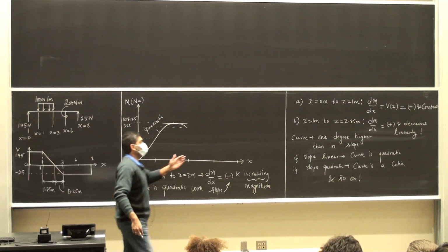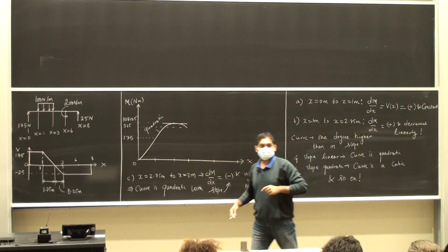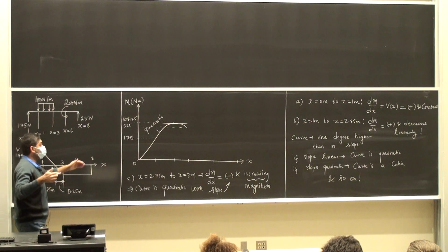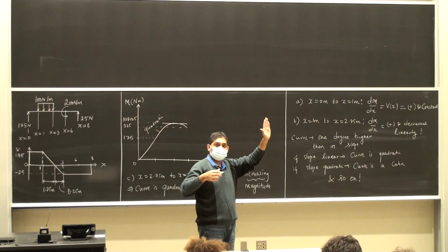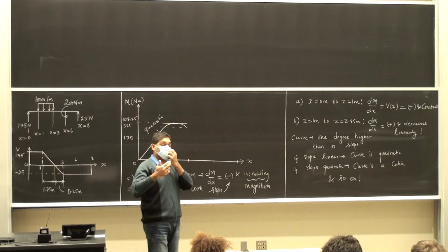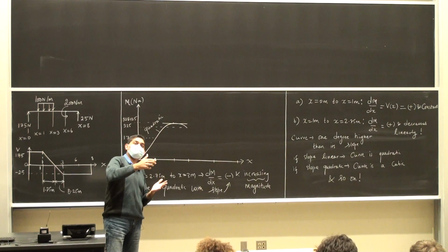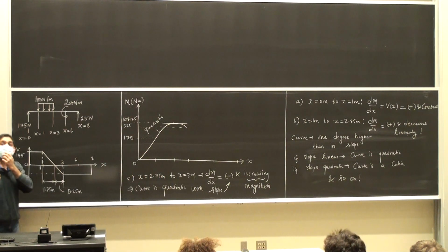And when I said likewise here, I was looking only at the magnitude of the shear force. So account for the sign of the shear force, which is going to tell you whether the slope is falling down or climbing up. And then account for the magnitude of the shear force, which will tell you how the slope is changing. Is it positive and decreasing or increasing, or is it negative and decreasing or increasing?